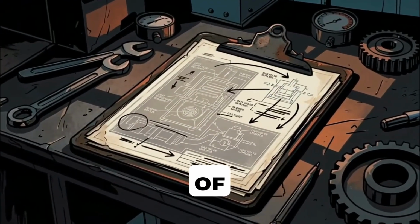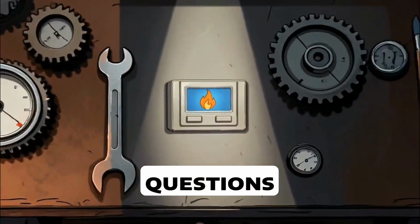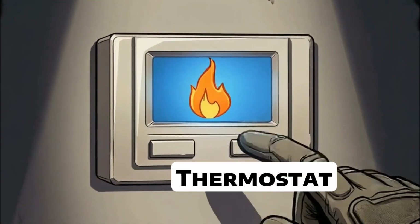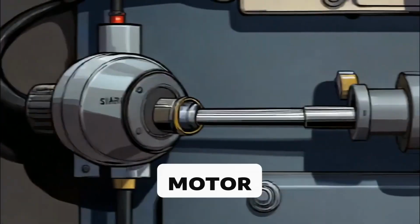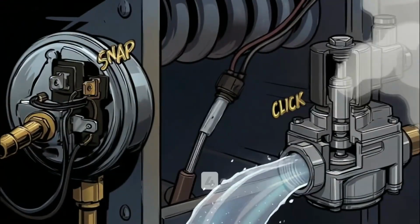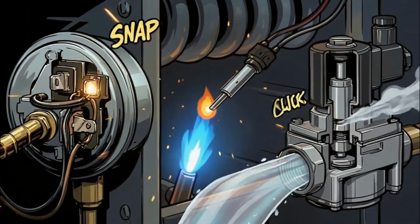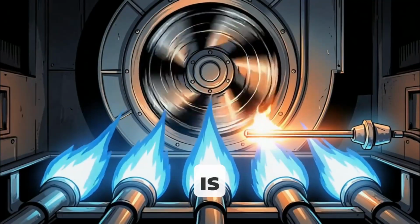Now, the sequence of operation. This is critical for troubleshooting and exam questions. Step 1. Thermostat calls for heat. Step 2. Inducer or draft motor starts. Step 3. Pressure switch closes. Step 4. Ignition begins. Step 5. Gas valve opens. Step 6. Burners ignite. Step 7. Flame is proven.